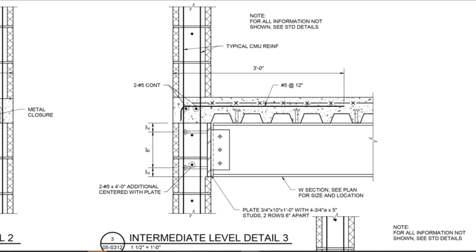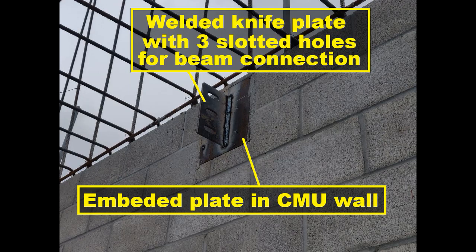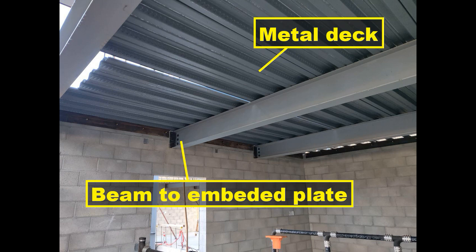In the attached pictures, you can see the embedded plate before installing it into CMU wall with 4 welded studs. The next picture shows the plate after being installed and grouted into CMU wall with welded knife plate to secure beam with TC bolts. Last picture depicts beams in place, the metal deck placed above the beams, anchors and angles attached to CMU wall to support the metal deck.